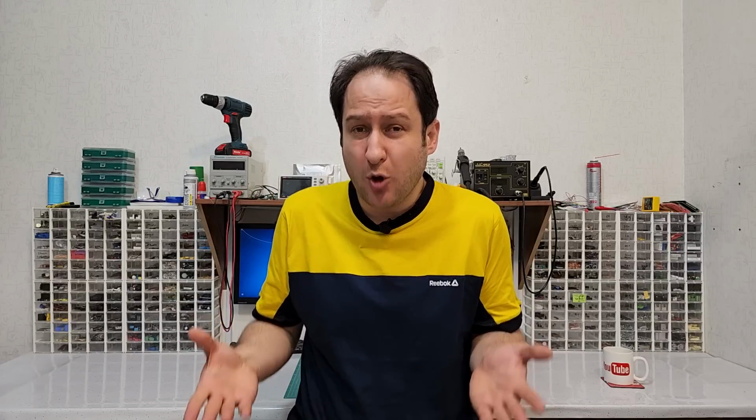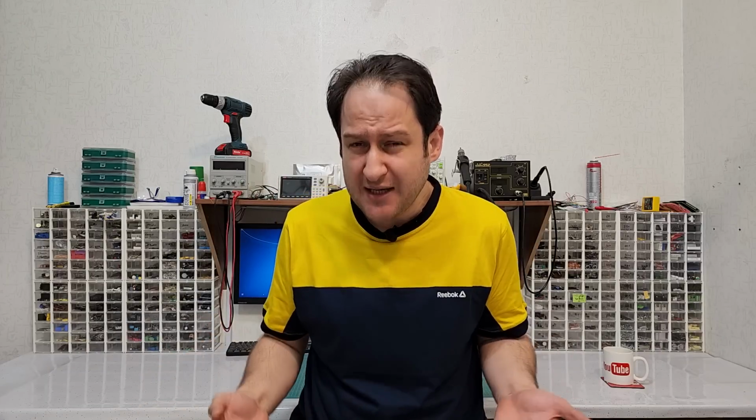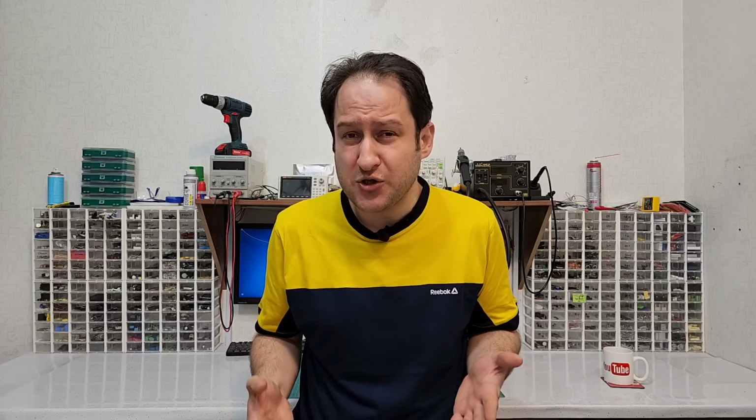If you think that it's over, I have to say no, we are not done yet, because there is a serious problem here. By decreasing the HFE, we have to increase the base current, and the base current has to be supplied by a low power source like a microcontroller or a sensor. The GPIO of a microcontroller can provide up to 30 milliamperes of current, not more. So we have to increase the HFE to decrease the base current, and this will cause the transistor to get hot. What can we do? Surprisingly, there is a simple solution for this problem.